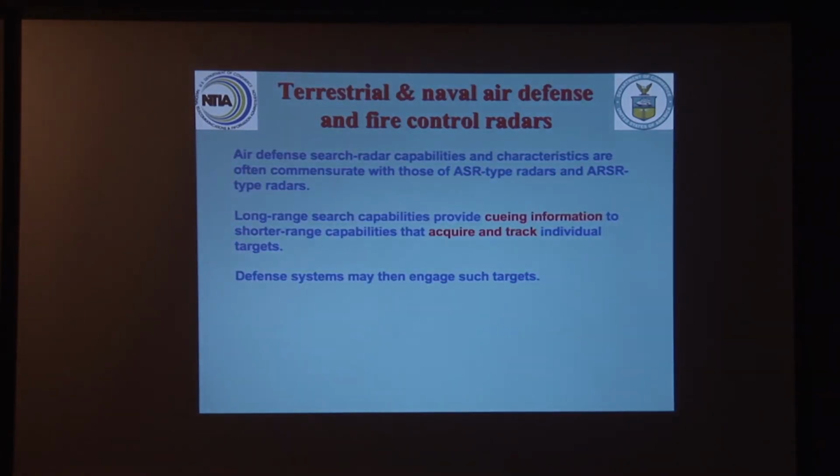Now this segues into air defense and fire control radars that are used on land and used by naval forces. Basically, in any air defense system, there has to be a search radar capability, which does what the ASRs and the ARSRs do. They have to continually scan around and around, updating every 5 to 10 seconds, give or take, looking for anything out there. And if you need to, you get the airborne systems up so they're looking down.